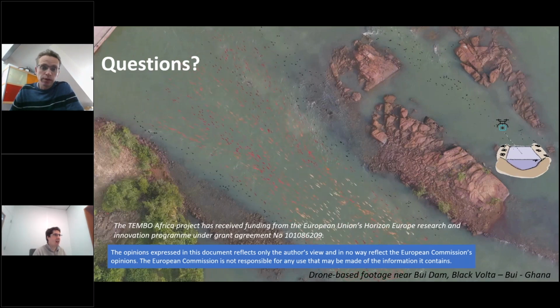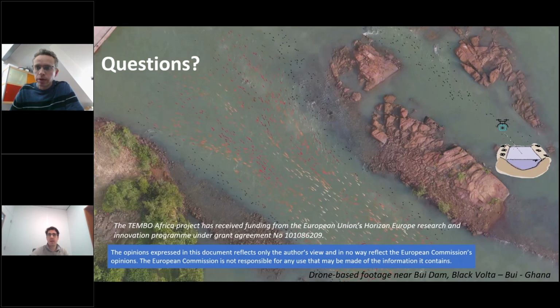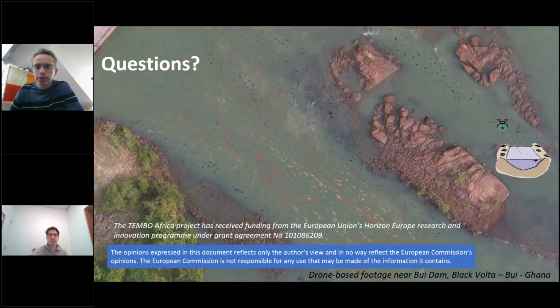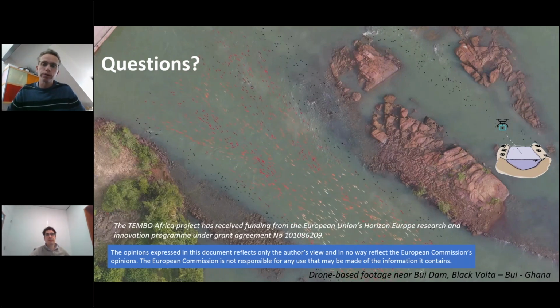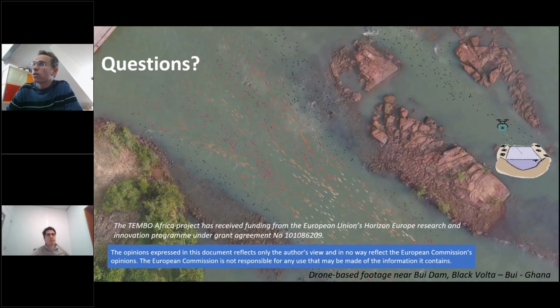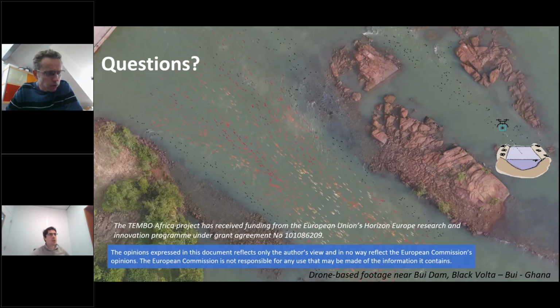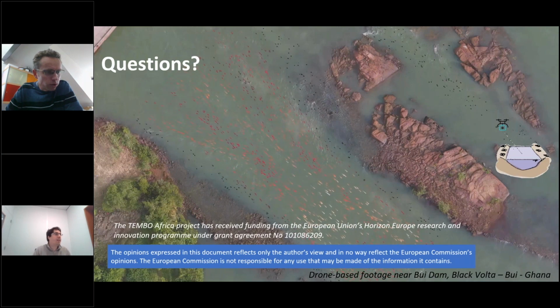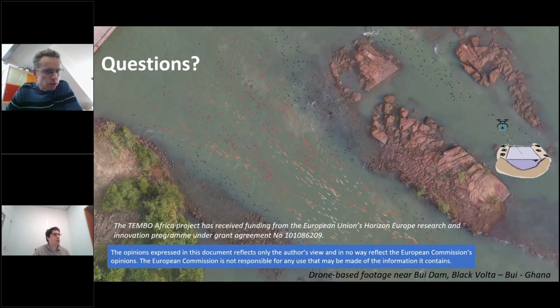So we have a stabilization approach that uses recognized corner points to stabilize. It's also split up in quadrants so that you have stable points in every quadrant of your video. And then the second small question, sorry, what was the second question again? Yeah, how are the uncertainties of these drone velocimetries in low flows?